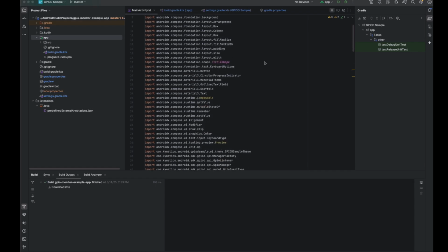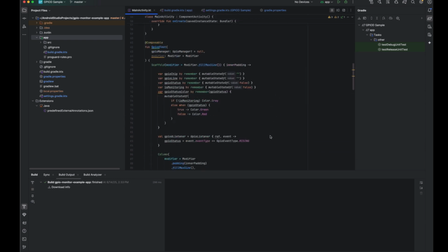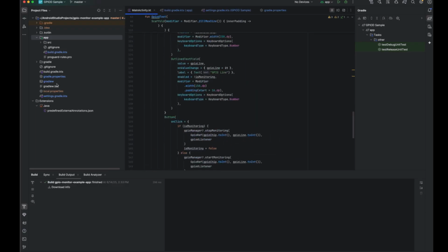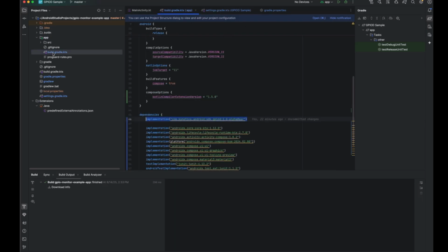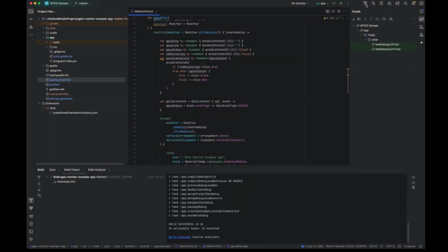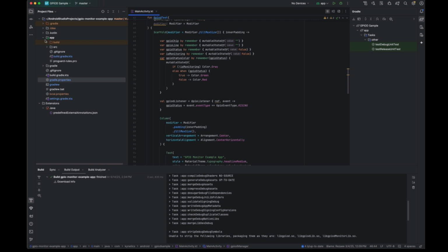Because then these libraries will be part of your toolkit. You will be able to integrate those libraries in your application seamlessly, because we provide a Maven repository. You just need to add the library in your build Gradle configuration, and then you're ready to write an application that accesses those low-level buses. In particular, here we are showing an application built to monitor the state of a GPIO.